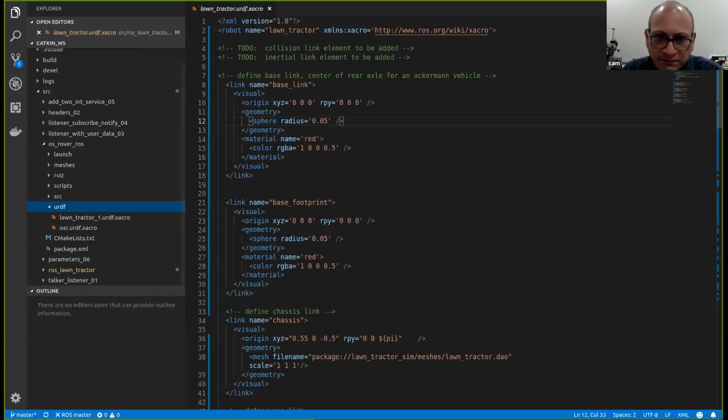So here, how you define a link is, well, Matt and I had an interesting conversation on the Ackermann vehicle, and how the center of rotation and the center of the body, and how the Ackermann should take the instantaneous center of rotation, and then how we put the base link right there so that we can mimic the Ackermann vehicle with the steering, so that's the whole purpose.